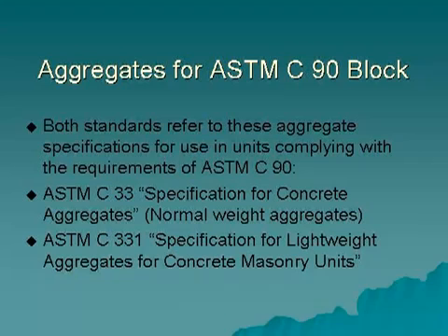In this case, the block manufacturer would submit test reports on the concrete masonry units they intend to ship to a given project. In the case of ESCS, manufacturers can request test reports showing that expanded shale lightweight aggregate complies with all the requirements in ASTM C 331.